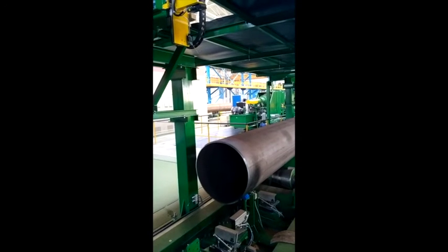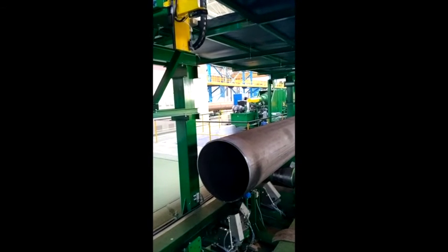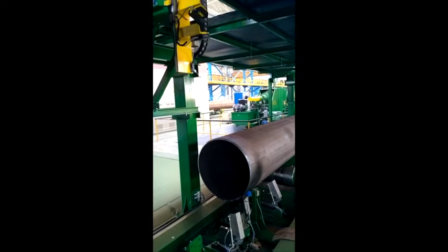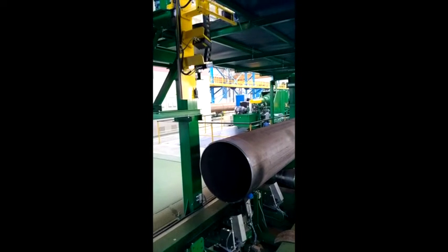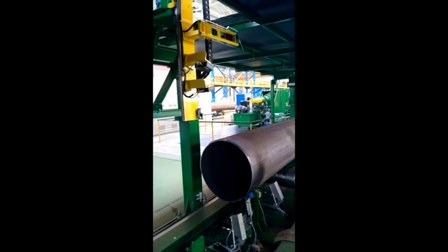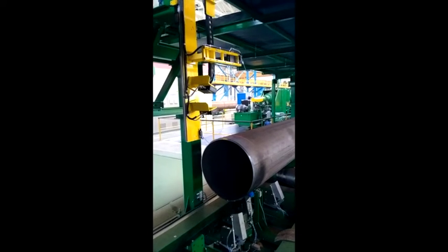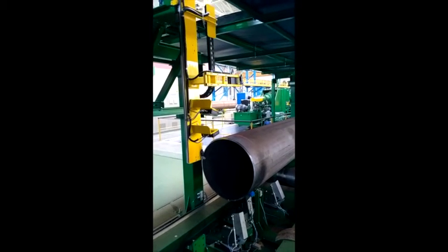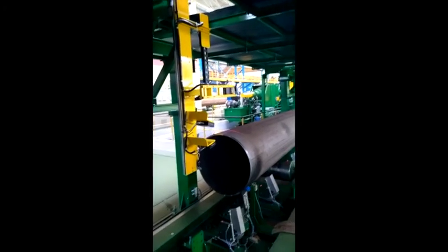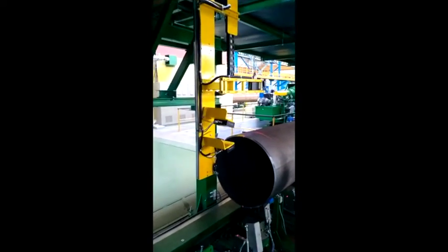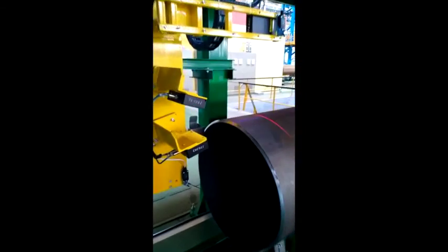Now we will see an example of inspection of pipe end parameters. For this purpose, the pipe is automatically positioned in the place of the roller track where the inspection is made. The pipe is lifted on elevating rollers. The manipulator puts down the laser sensors. The laser sensors, which are located beneath the pipe, are protected from the penetration of foreign objects and dust by special screens, which are opened automatically by the sensors' operation.